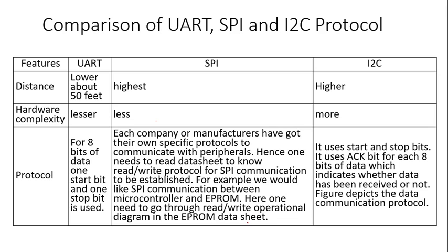So hardware goes on increasing, but as far as software is concerned, there is no overhead present in the SPI protocol. Then the I2C. I2C uses start bit and stop bit, and it uses an acknowledgement bit for each 8-bit data, which indicates whether the data has been received or not.